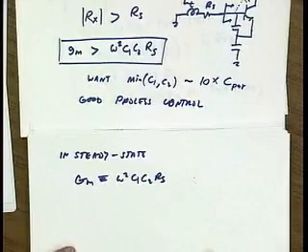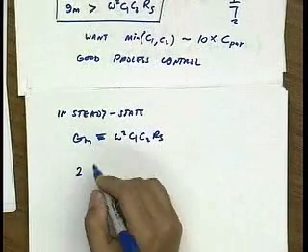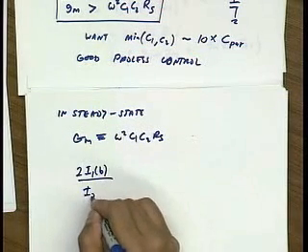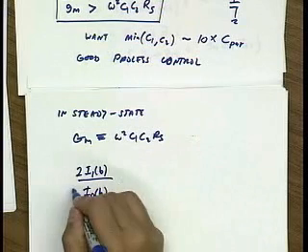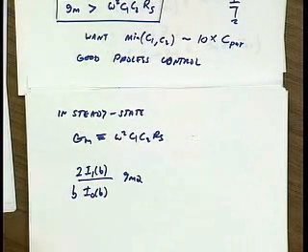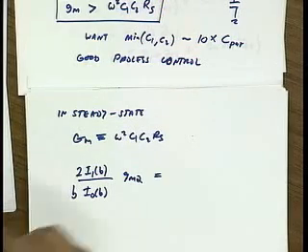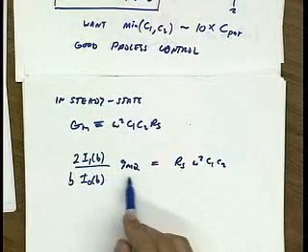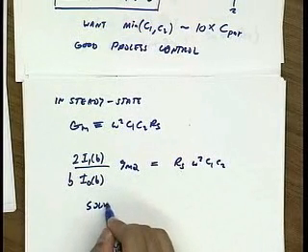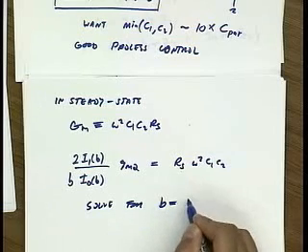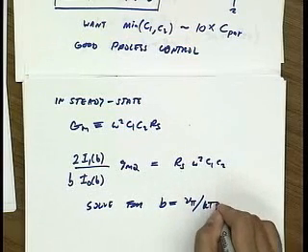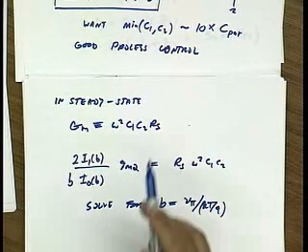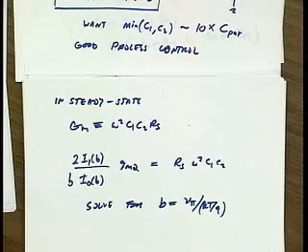And if this were a bipolar transistor, I know that the large signal GM is basically given by these modified Bessel functions times the small signal GM, and here I can solve for B, which is equal to V pi normalized to kT over q. So I can solve for B, and once I know B, I know the oscillation amplitude.